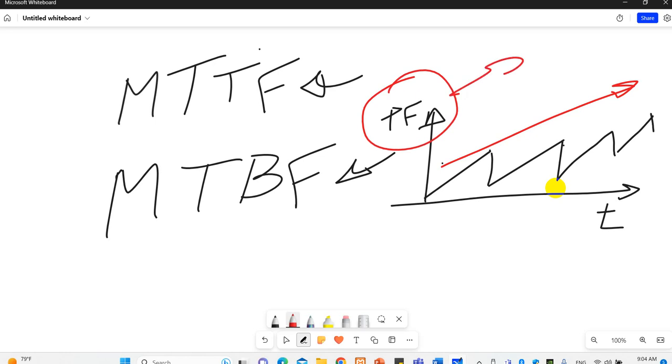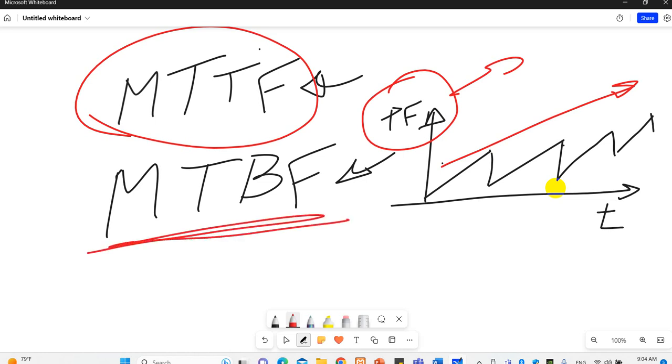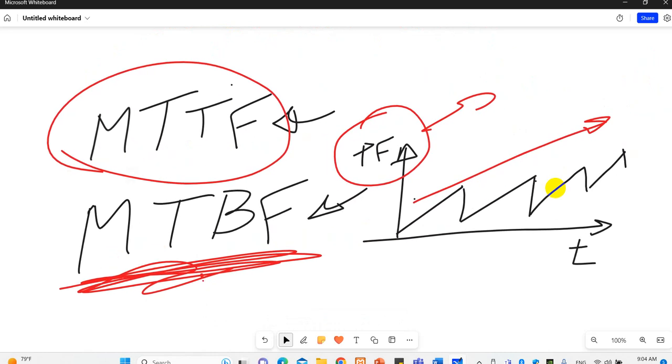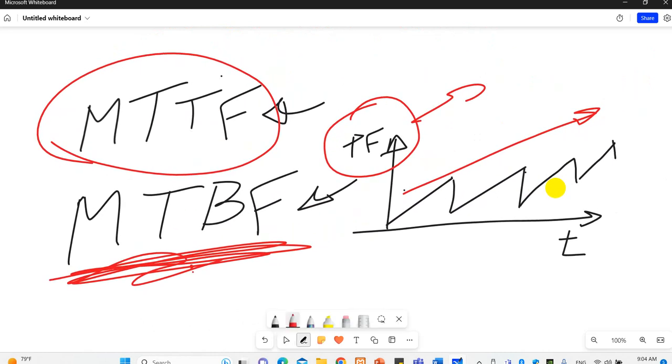Okay? But for mean time to failure, that means you are not using this part again, like an air filter, like an oil filter, a belt. What happens to a belt when it cuts or when it wears? You replace it, you throw it away. So you can't say mean time between failures because it's not the same part, it's replaced. You say mean time to failure.